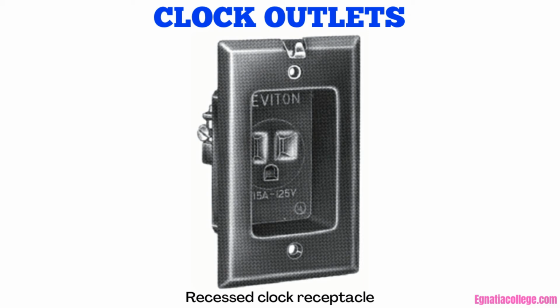Clock outlets. A deep sectional box is recommended because a recessed clock outlet takes up considerable room in the box. Some decorative clocks have the entire motor recessed so that only the hands and numbers are exposed on the surface of the soffit or wall. Some of these clocks require special outlet boxes, usually furnished with the clock. Other clocks require a standard 4-inch square outlet box.